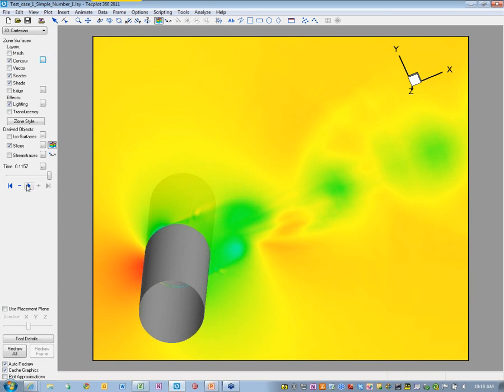And this is exactly what drives a lot of the aeroelastic problems, the flutter problems that you have on aircraft as well as on buildings, bridges, cables. This is a big problem I know in the petroleum industry, where they have cables holding these offshore drilling rigs in place, and so this is a significant problem. And then again, one of the great things about having the additional computational resources is now you can study them in a more dynamic sense.